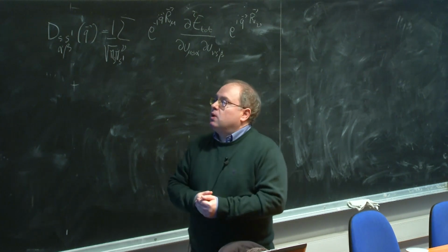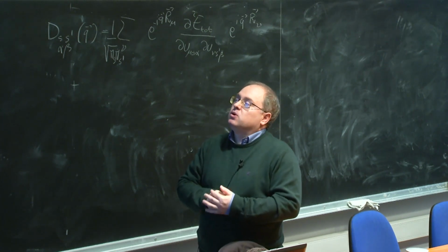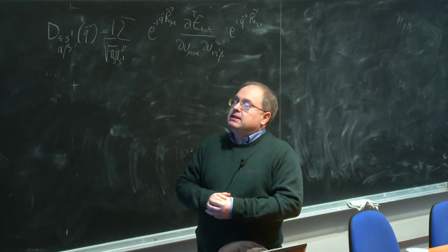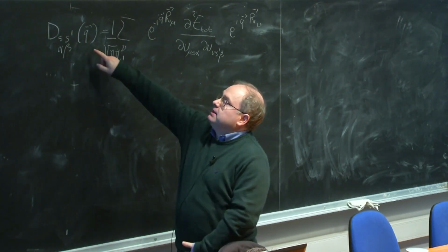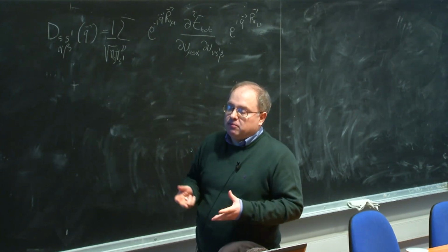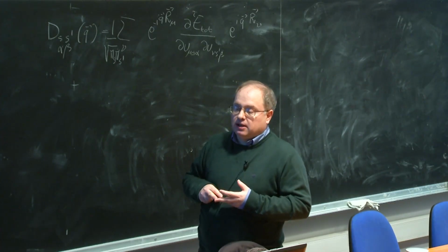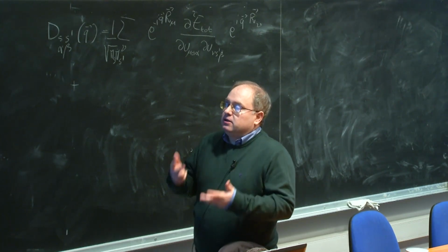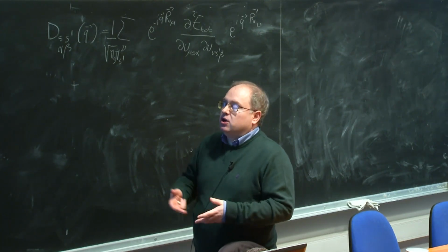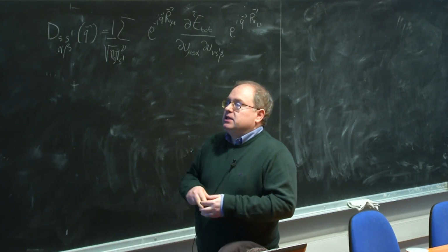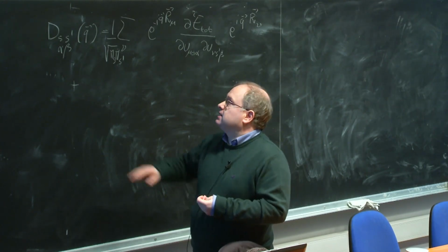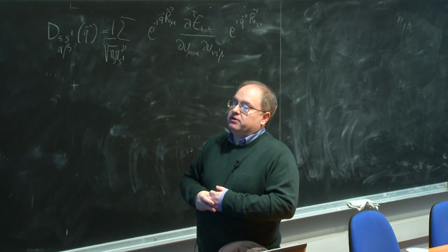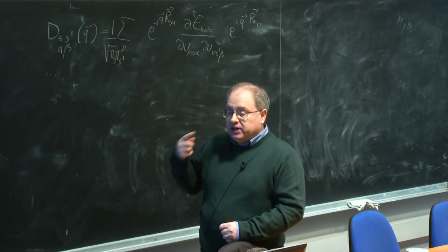So point number 1, the phonon code. The phonon code is called ph.x in Quantum ESPRESSO. It reads the input of PW. First you have to do a self-consistent calculation with PW, and then the charge density, the wave function, and the geometry are written on a file. This phonon code reads this file, sets up the dynamical matrix with the expression that we have seen this morning, and it is solved for each perturbation.